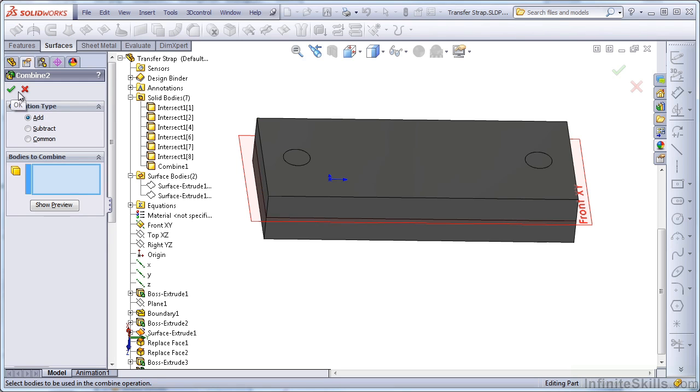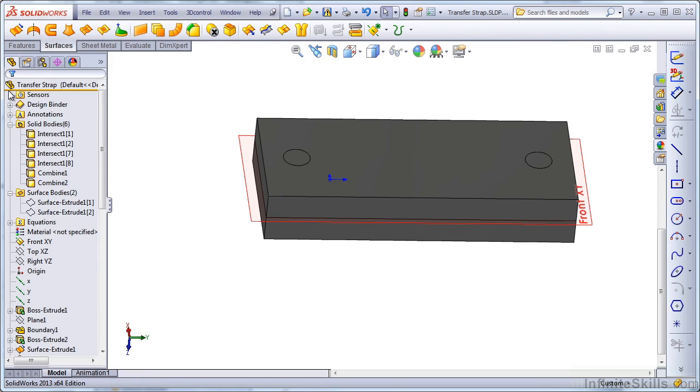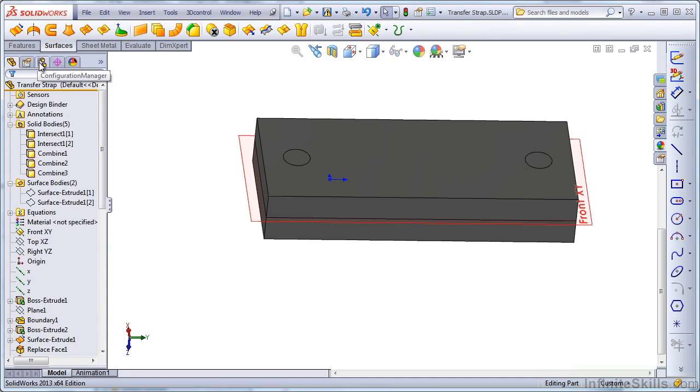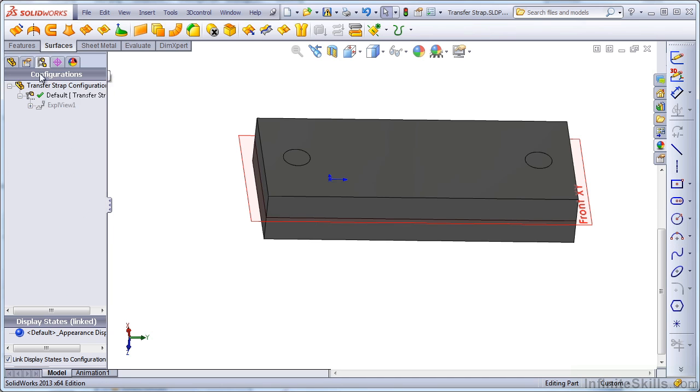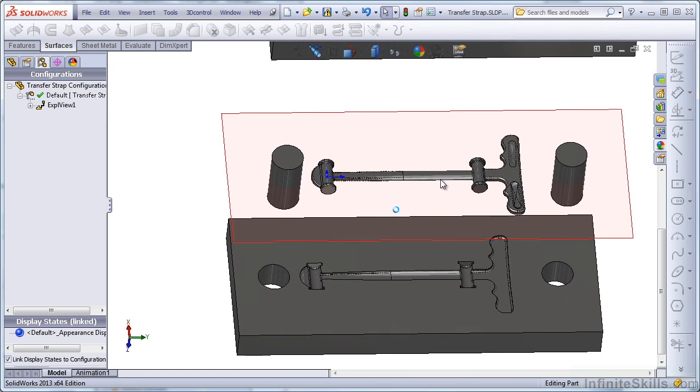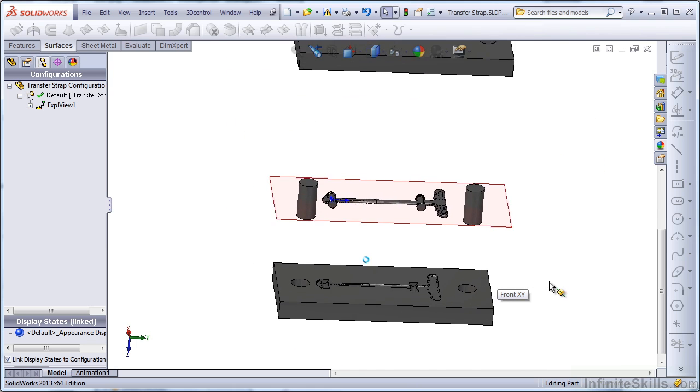to restart the same command, and we'll select that part of the pin and this part of the pin and join those together. And one more time, we've got a top half of the actual part and a bottom half of the part as well. Now we go back and explode the exploded view, and our pillars are a single piece, our part is a single piece, and we've got a top and bottom block for our die.